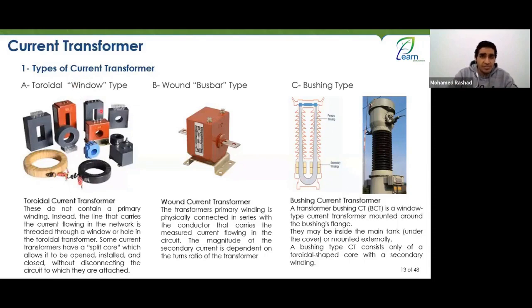The idea here with this current transformer, remember I told you we would talk about each part separately. I just mentioned that the primary winding is connected in series in my circuit, right? Very good. But this type of transformer, which we call the window type or the toroidal type, doesn't have a primary, meaning the CT that I buy is essentially a core, which is the part I'm talking about. This is the core, whose details I haven't discussed yet, and the secondary windings are wrapped around it.